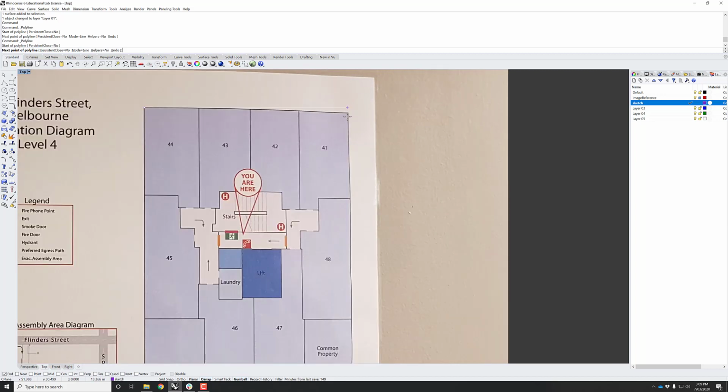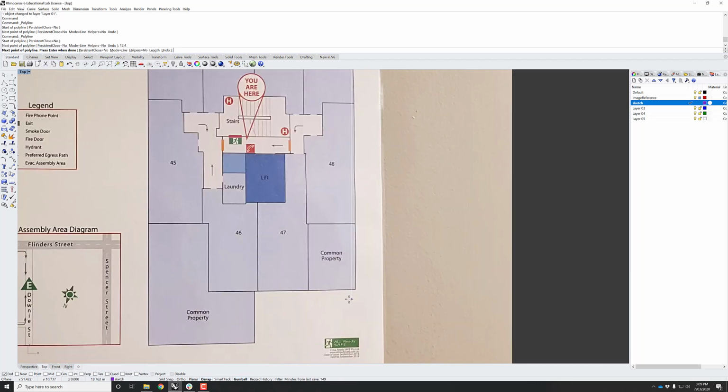And then if I wanted to type in a length for that line, it looks like this is about 13.5-ish or 13.4. So I'm going to type in 13.4 rather than approximating the dimension. Type it in so that we don't get any weird decimals. The same deal for here, so we get 19.2.